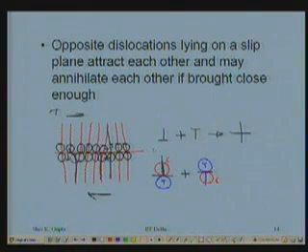When they come together, a negative strain and positive strain add because of the vectorial addition of this, and therefore the net displacement can become 0 and ultimately I end up with a crystal without any strain whatsoever. There are no strains in it. It becomes strain free. Compressive strain cancels the tensile strain here and this tensile strain cancels the compressive strain here, and this is a common slip plane. You get a perfect crystal.